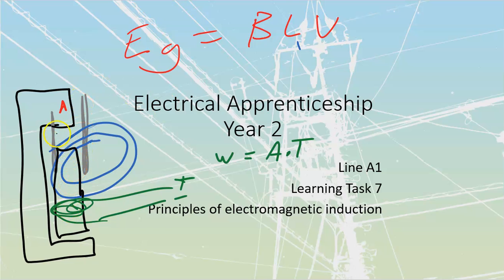The number of flux lines, when they get up to here, those flux lines are going to do a little bit of fringing, where they bulge out as they go through there, which is going to decrease the flux density, right? They're less dense because they're bulged out a little bit, but I'm still going to have a decent amount of Teslas. Teslas is just the measurement of the number of lines of flux over top of the area. So we have lots of lines of flux generated, our Webers through our ampere turns, but then they're going to spread out, which means that my Tesla value is going to be a little bit decreased as a result.